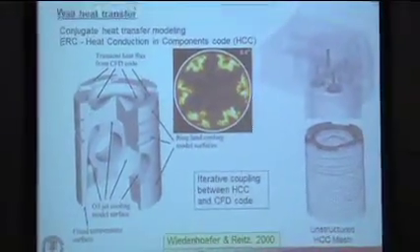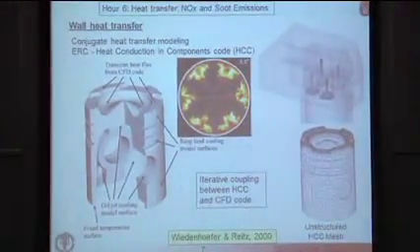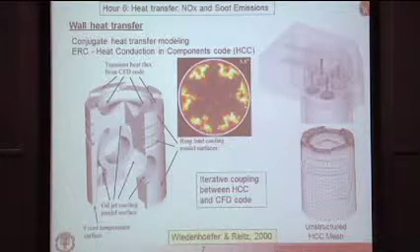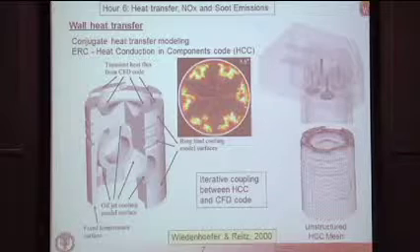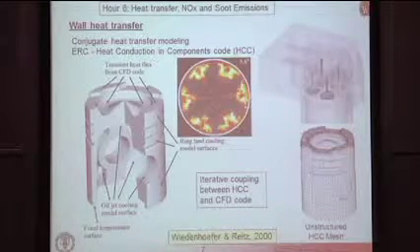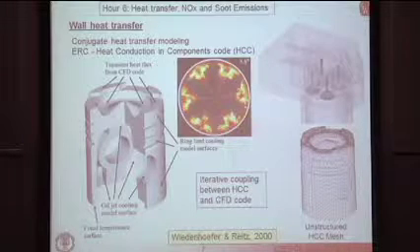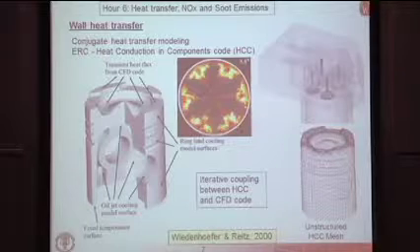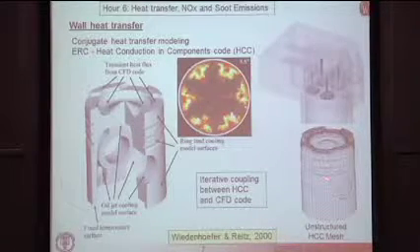Okay, so we have now heat flux that is coming from the gas phase. We have both due to temperature gradients in the vicinity of the wall, and then also due to radiative flux to the surfaces. Just a picture showing that you could expect quite a lot of radiative flux from conventional diesel combustion. And what we've done is to basically integrate that with a finite element heat conduction code for the metal components in the engine.